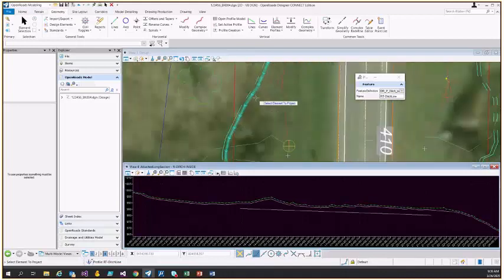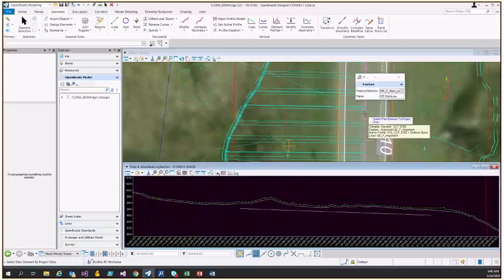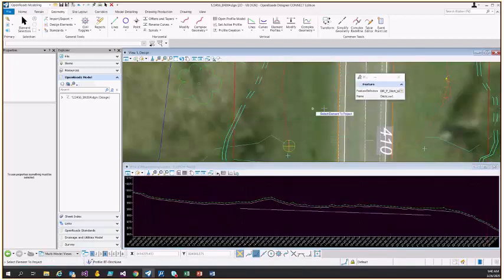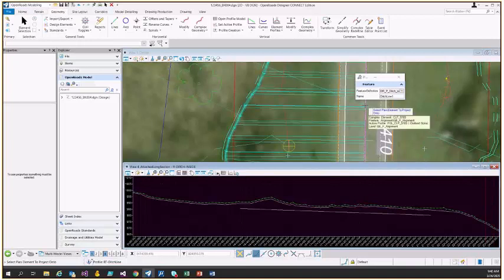If you just come here and choose this one, it's going to take the template one. If you draw in another one, then you have to come into the profile and physically select that to project it. You select that, and then come over here and click what you want to project onto. I'll just do both of them for demonstration purposes here.